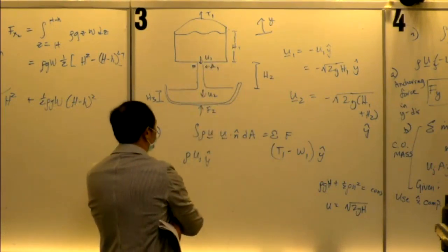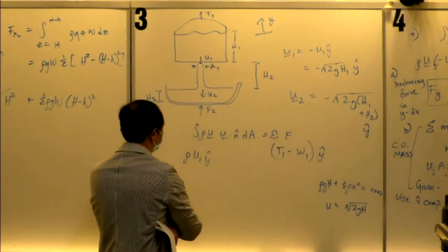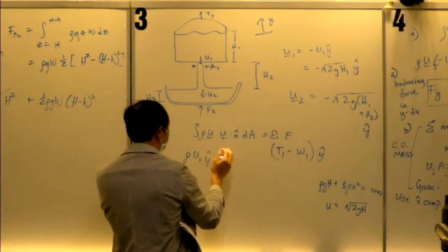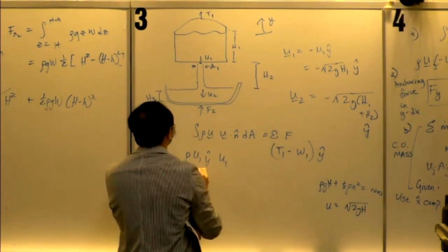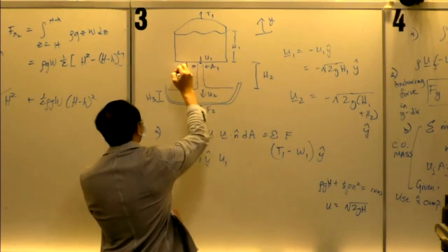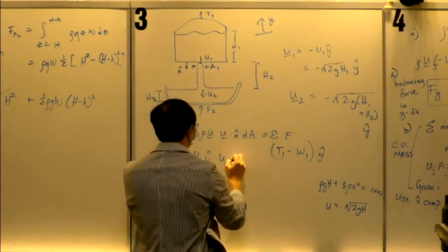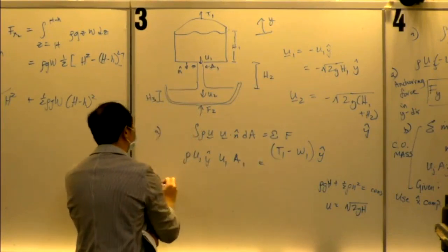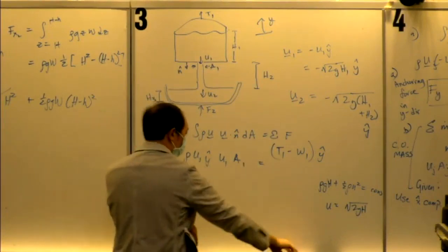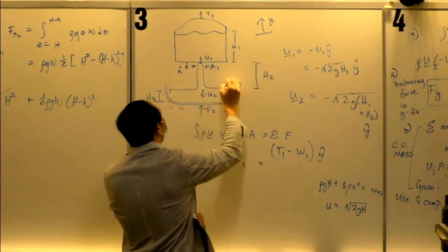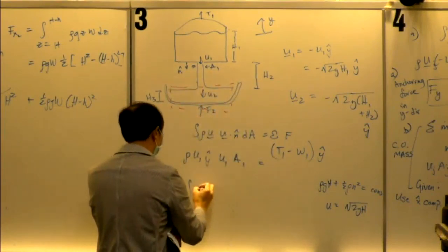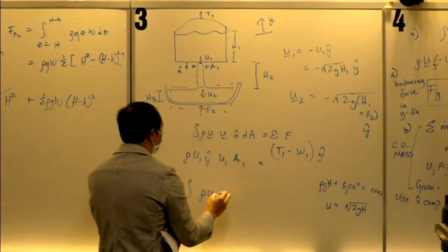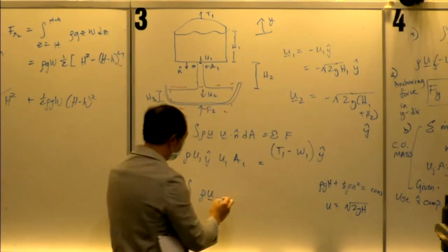All right, so for part A, you have that equation, and u dot n is just magnitude u1 n hat times a1, right? Equal to that stuff. But for part B, the problem is it's got a higher speed. So you got rho u2, the amount of momentum it has, but the flux is not at that higher speed. The flux is still from conservation of mass.